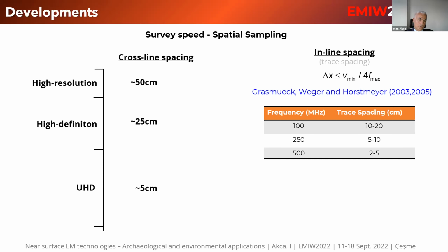And for sure it's dependent on the frequency we use. I mean, the trace spacing and also the line spacing are dependent on the frequency we used. As you remember, the lower frequency means higher penetration depth, and the higher frequency provides the high resolution. So the trace spacing and line spacing is set up accordingly.